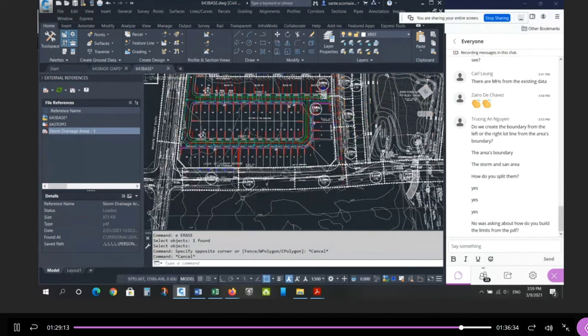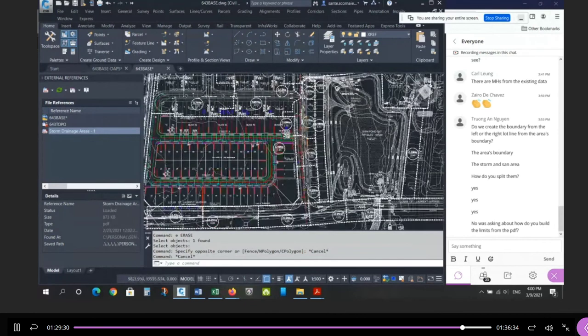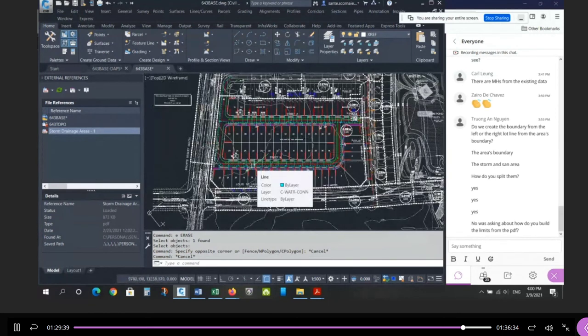I'm going to see if we can get away with it this year because these pipes are new and they're all designed to go into the same pond that the rest of the site is going to. So the pond is designed to take that total flow. It's just a matter of which route. Are we going to take all this through this area, or all of the road plus some backyards through this area? At the end of the day, they all go to the same pond, so I'm not worried about the final destination. I'm worried about the route.